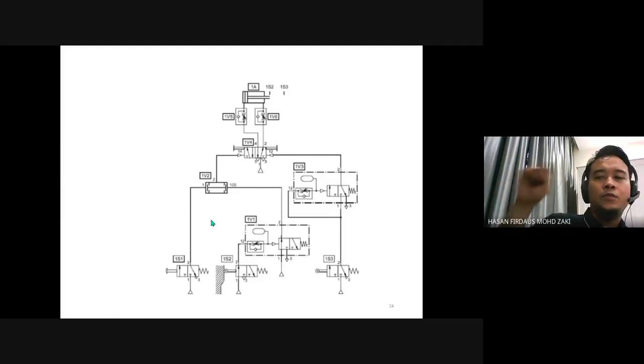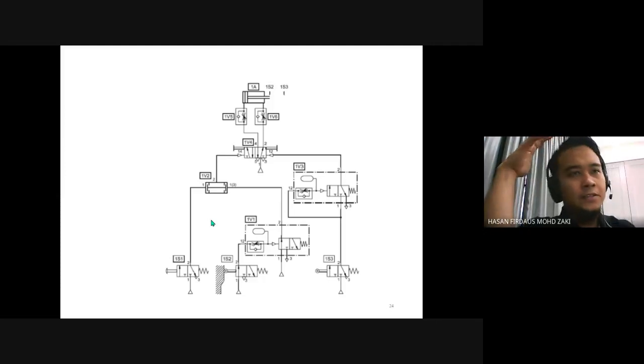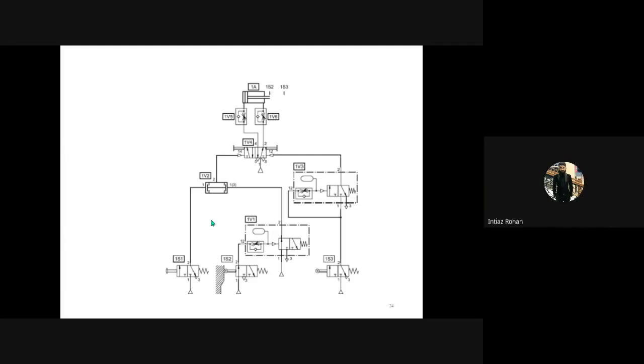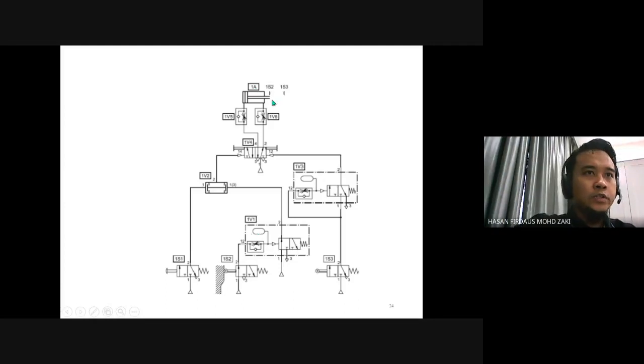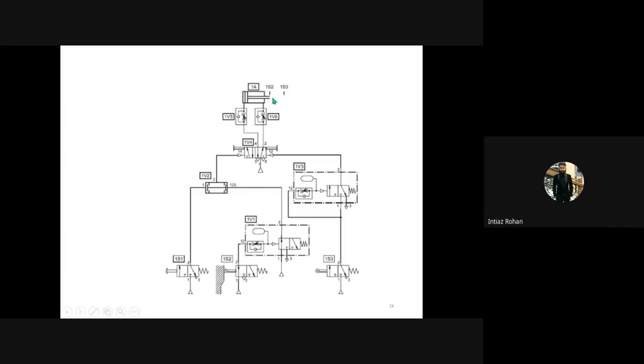If you press the push button, it will wait for 5 seconds, and then it will start. And if we put it on 1S2, what will happen? If you put here 1S2, you detect the full retraction, right? So it's not the full, it's the immediate, like the preliminary point. So it will always be triggered, 1S2.